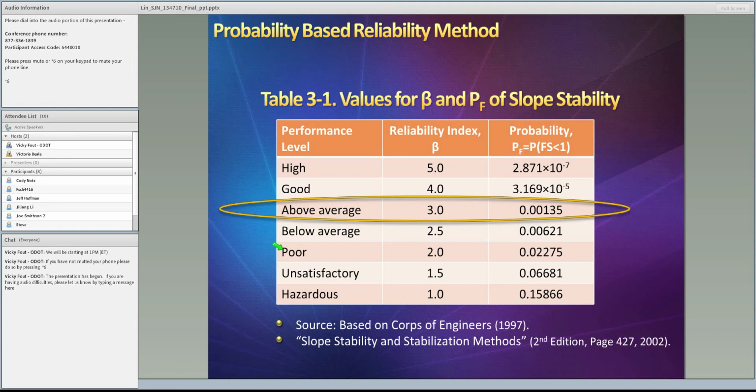Also, for the probability density function of the soil parameters, we're using the log-normal distribution. The mean and variance are based on the soil boring test data. All of them follow IID, an independent identical distribution, which means there is no correlation in the soil parameters for every layer and every parameter.